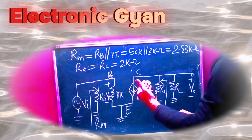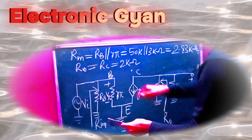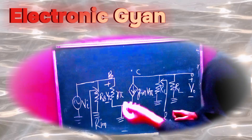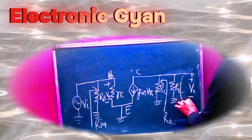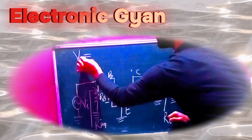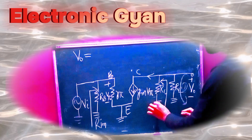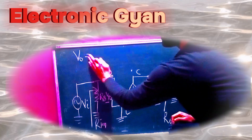Now we are going to calculate the voltage gain of a common emitter amplifier. So let's see here. Again, I am going to rub this, because this circuit I want to keep with me, so that I can see it properly. For voltage gain, first of all, I am going to apply KVL in this outer loop 1. So therefore V0 is equal to how much? This current is going like this, coming from down to up, means positive to negative. So if I apply KVL here, what will I get?